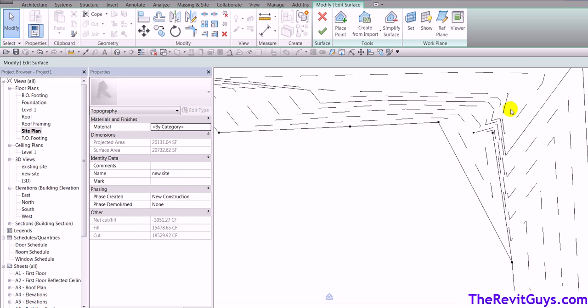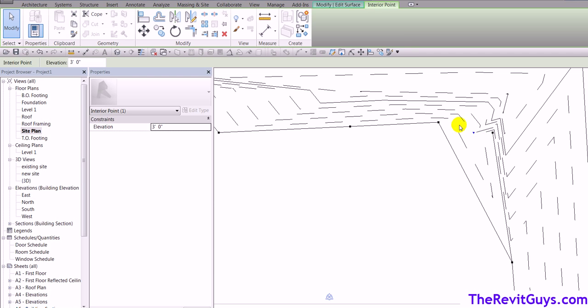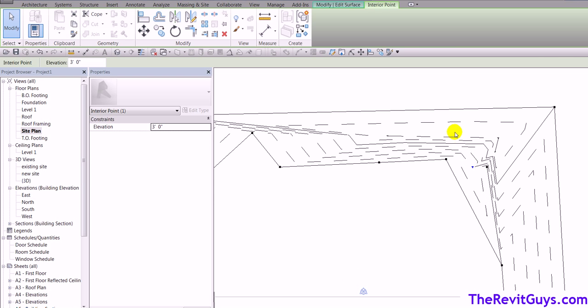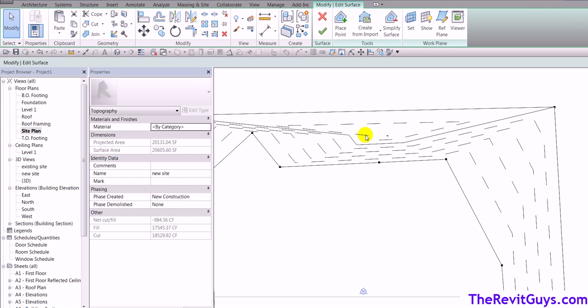If you want to kind of relay this area out, you could, but instead of dragging points or editing points, you could actually delete these points in here and just redraw them correctly. So to do that, just grab them like so. Go ahead and just delete them. Now they're deleted, you may say, well, I'm going from 5 feet maybe down to 3 or 4 feet around here. So we can continue to place points to set it how you want to make it.